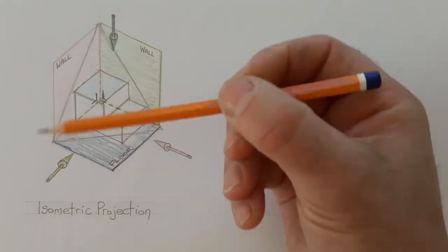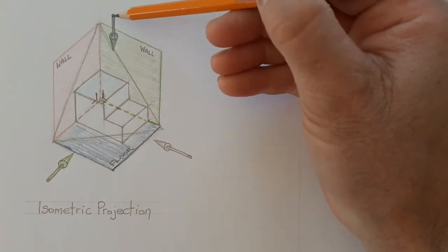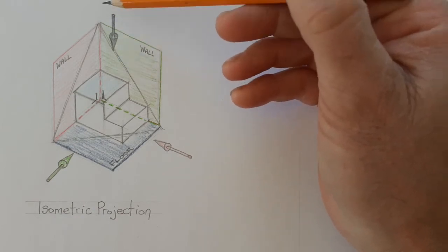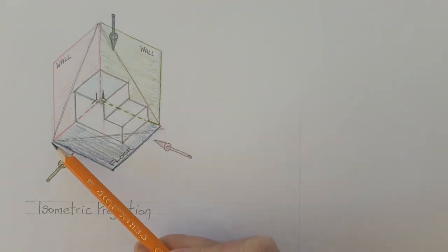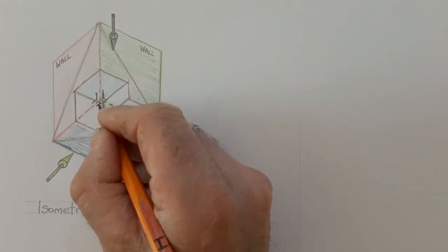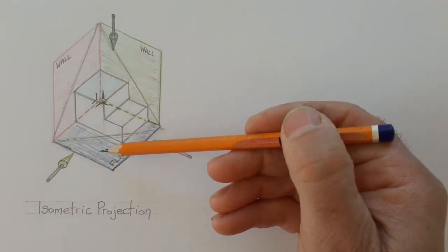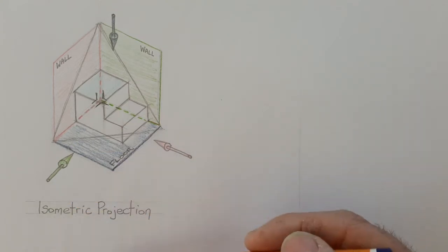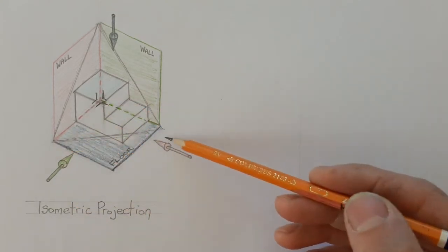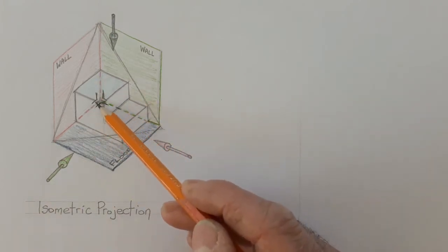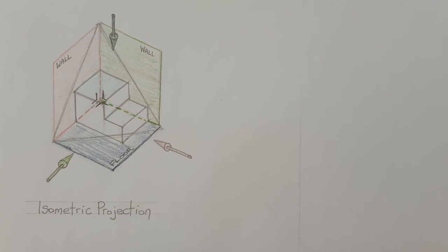because this in reality is a 90-degree angle. Finally, if we look down from the blue arrow direction, so we're now suspended above the floor looking down, I know that the corner here where the floor meets both walls, in reality, is going to be a 90-degree angle. So when I project down the true shape of the floor down here, I'll be setting up a 90-degree angle because that's what it is in reality. So we have a 90-degree angle there, a 90-degree angle on the floor, and a 90-degree angle there. And I'm going to run through the setup of that in a minute.